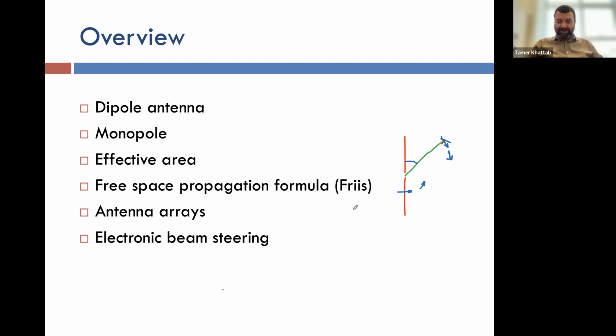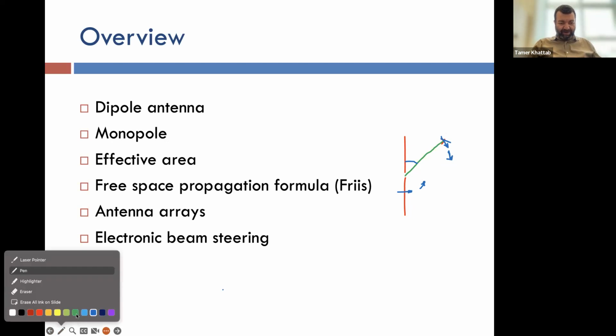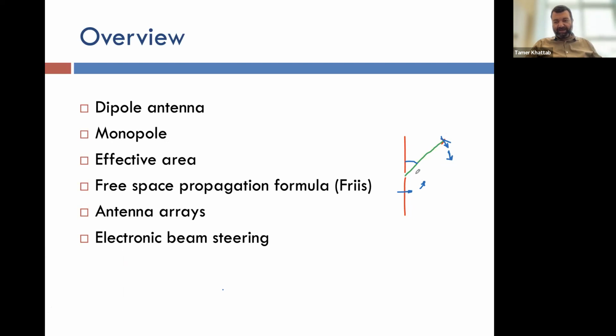Expressions, you don't need to memorize them, but the end result, because of this direction in theta and this direction of phi, when you try to figure out where the signal, or the energy of the electromagnetic wave, is propagating, you will find that it's propagating in the direction of R. So this is how your signal travels. This is how your power transfers from one point to the other, right? So it moves in all radial directions. That's where your power is going out of that antenna.